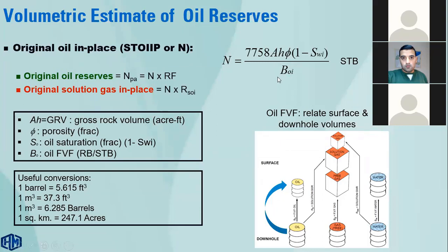Simply, the initial oil formation volume factor term is used to convert downhole volumes to equivalent surface volumes, because the volume of oil, for example, will be reduced from the reservoir, or from downhole, to surface due to mass losses, because more solution gas will be released while we have a reduction in flowing pressure from the bottom of the well to the wellhead.